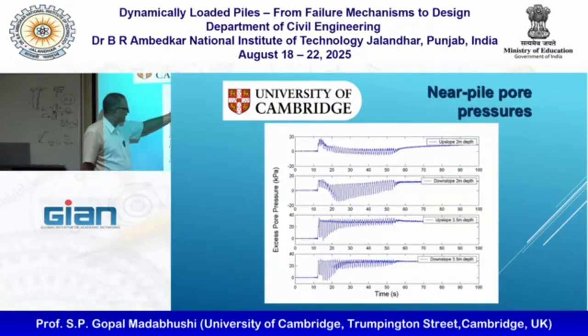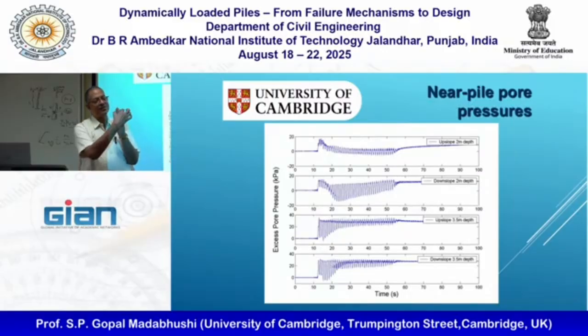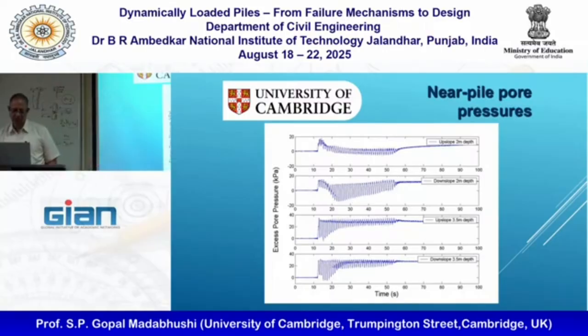This is getting less of an issue as you go deeper into the slope. These two look a lot more similar than these two, right? So the pile is trying to bend, and here at this shallow depth they're very different, whereas at a deeper level they're similar. And the deeper we go, the more similar they will get. Agreed? That's what the data is showing us.